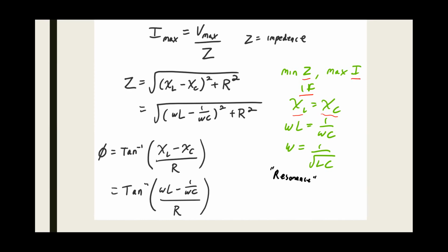So that's the frequency where the inductor and the capacitor effectively cancel each other out because they're not really resisting what's going on. They're happy to be oscillating at that frequency, which is the frequency they would oscillate if they weren't being driven. So that's kind of fun and interesting. But in no way do I have to drive an AC circuit at that resonance frequency. I can drive it at any frequency and the voltage and current will be functions of that frequency.